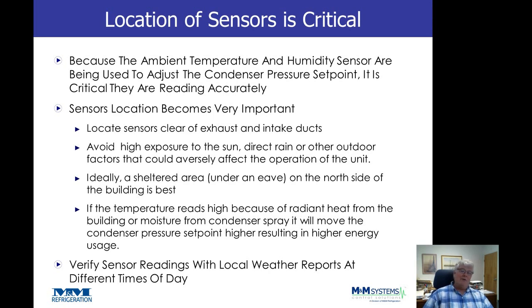I had one mounted to the side of a building. Every day the metal building heated up from the sun, it would cause the temperature to go up. Now it becomes very critical because as the ambient temperature would increase, so would the condenser set point, and when you could possibly be running a lower head pressure, the control would set it higher.